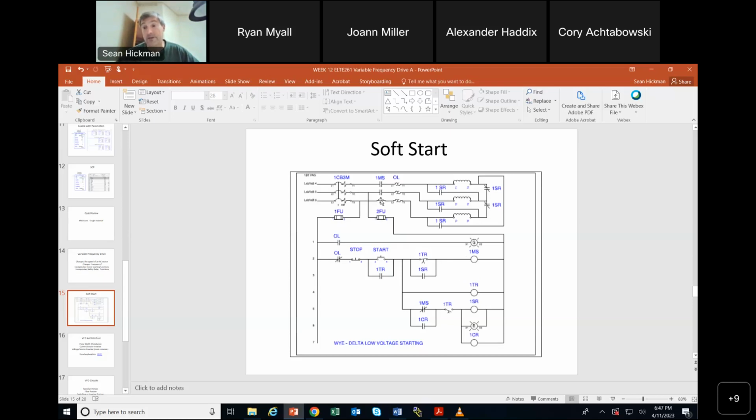Well, a VFD isn't going to have that. A VFD is going to have a hybrid parallel start that we already talked about, where it's going to have solid state contacts close, and solid state contacts don't have any moving parts. So the solid state contacts turn on. That starts the motor. And once the motor's running, then the real contacts close, and there's no spark at that moment because there's already a parallel path. And then the solid state contacts open, okay?